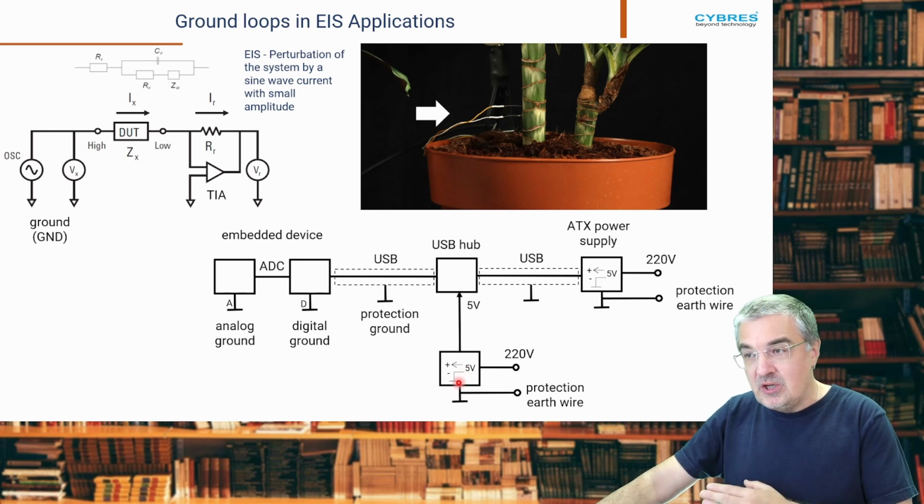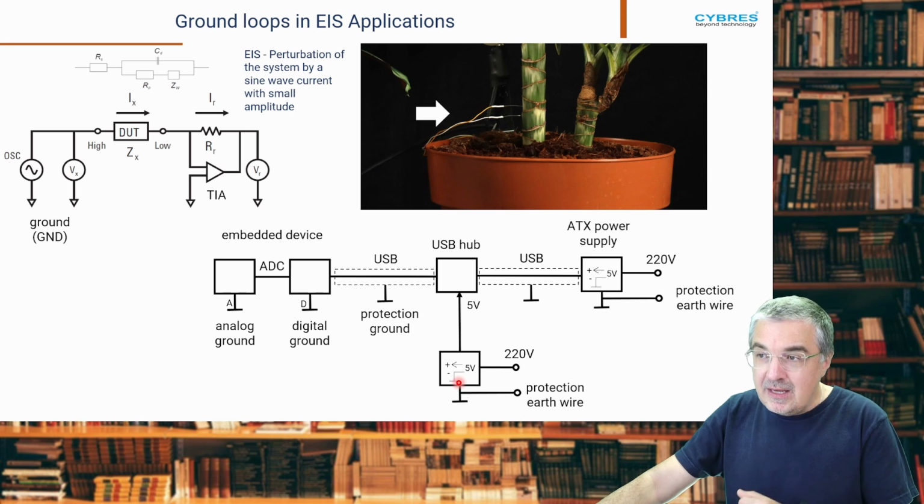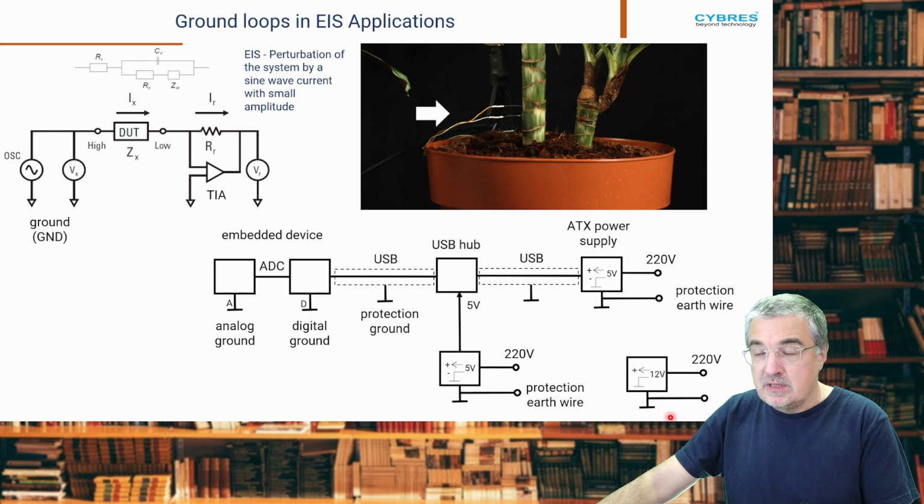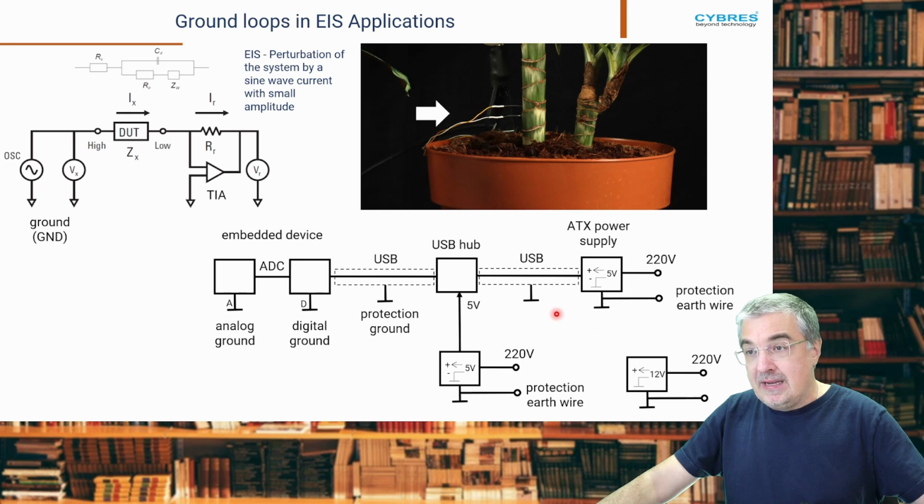And you know, this switch again produces noise, and this is continuous noise that should in fact be avoided. But a more essential issue is that this ground here and this ground here are not the same ground. Here you have a long line, it has some resistive part, some inductive part, capacitive part, and so this ground fluctuates in relation to this ground. Essentially, if you have multiple power supplies with common ground in your system, for instance, in our vertical farm we use a number of 12 volt supplies for the water pump and for LED lamps, and of course they also interact with the ground in your system.